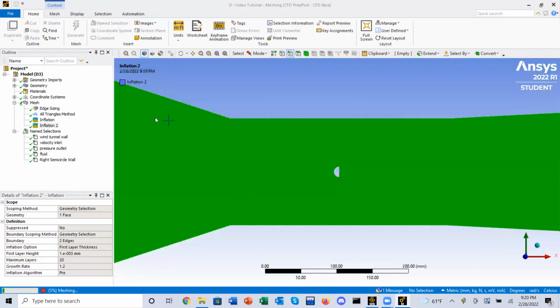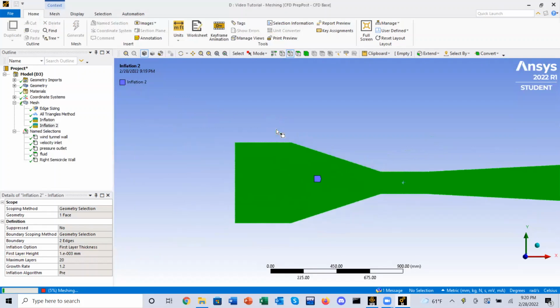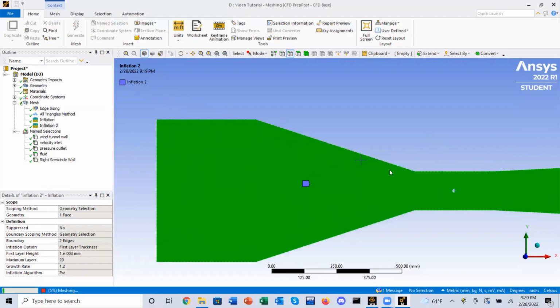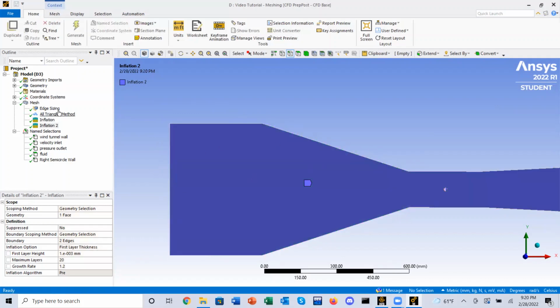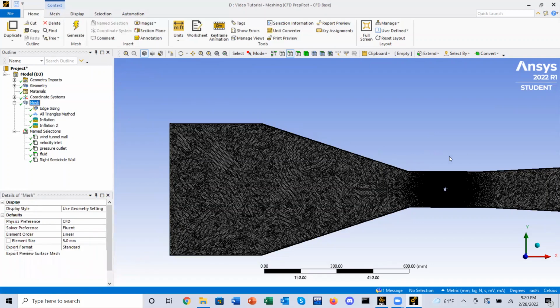Oh, one thing I wanted to mention actually, keeping it simple for this video, but ideally, what you want to do here is you don't want these rough edges for the transition in the wind tunnel. See those? So ideally, you could either just curve it a little bit, but if you want to do it properly, you can. NASA has like a flyer, I don't know, an old document, and it shows you the ideal. I think it's a formula, like a cubic formula, and it's the ideal curvature for this section of the wind tunnel, and that'll give you the most efficient wind tunnel possible. So you guys do want to take the time to do that. I do recommend it. So now when we click mesh, it should show us what the mesh looks like.